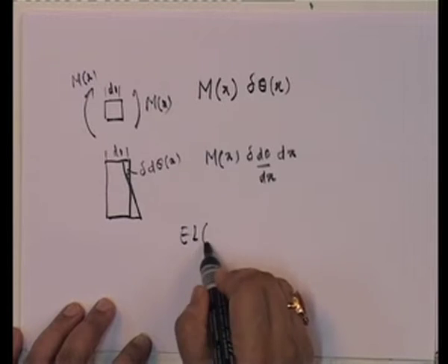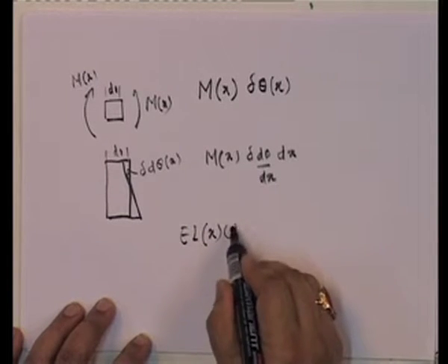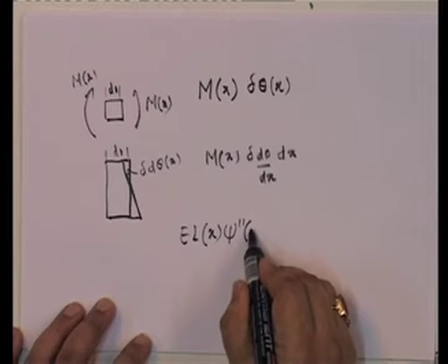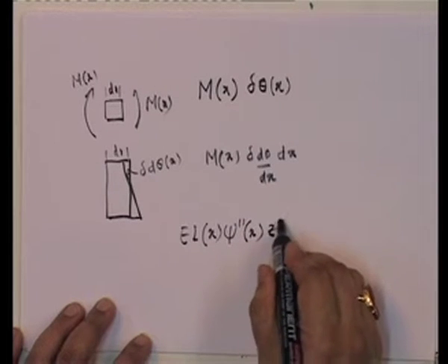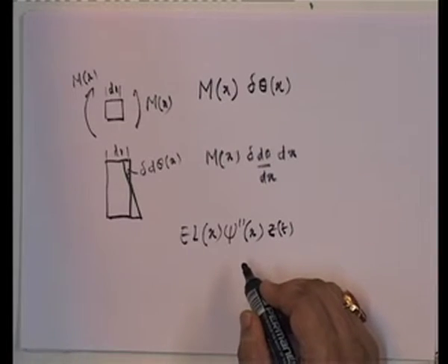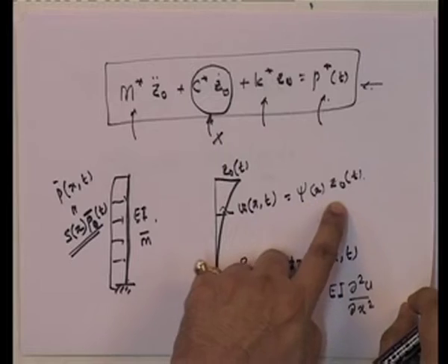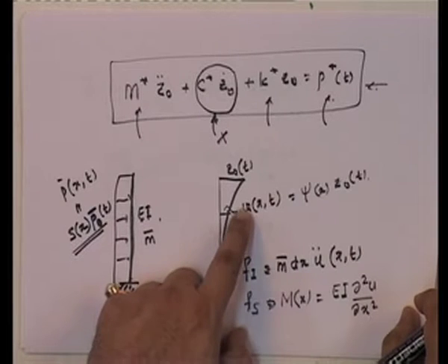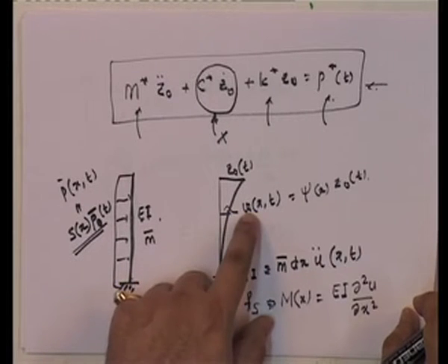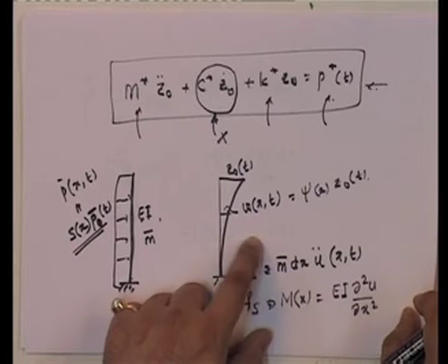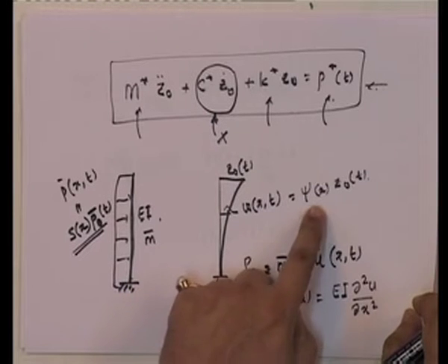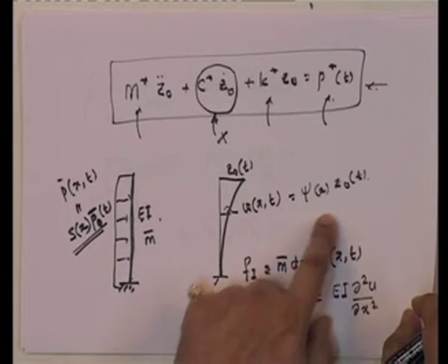Okay. Now, M, if I substitute, this is the work done by the internal forces. So, if I look at Mi is equal to Ei into xi prime z of t, because again if you look back, if ux of t is given in this form, u double prime, that is del squared u x of t by del x squared, is going to be just the d squared phi by dx squared into z naught.